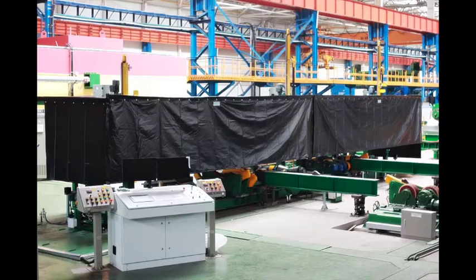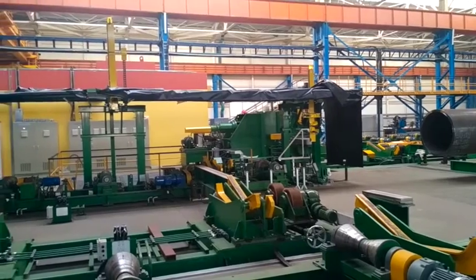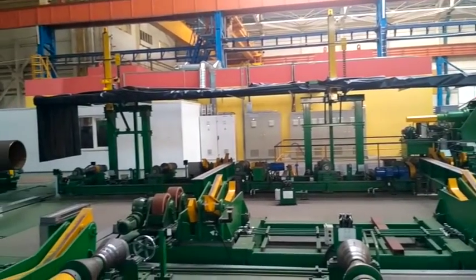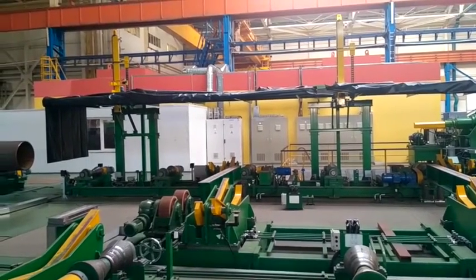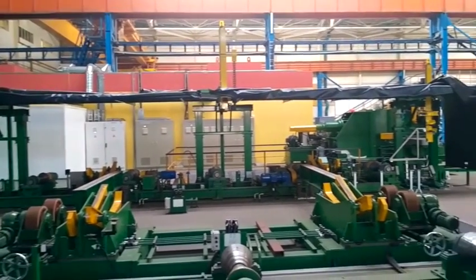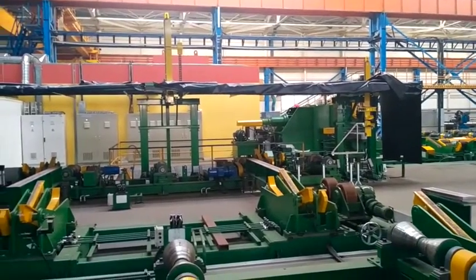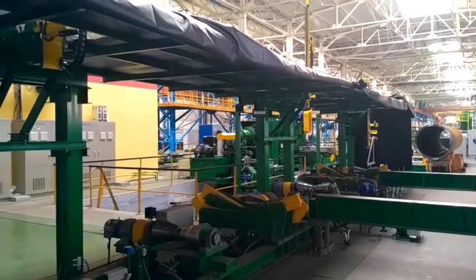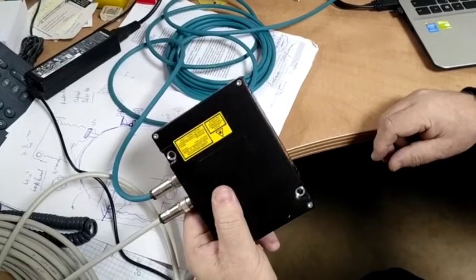This short film is made to demonstrate the work of an automated system for measurement of geometrical parameters of welded pipes. This system measures parameters of pipes with diameter from 426 mm to 1420 mm. The system's work is based on the triangulation method of detecting distances with the use of laser sensors.